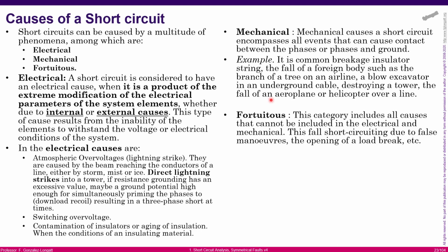For instance, at substation level, imagine that you have a circuit breaker and the dispatcher didn't realize that the circuit breaker was closed, and he tried to open the switch connected to that. Switches are not designed to interrupt currents, and as a consequence, you will create a problem with insulation, and then there is a single line connected to ground by a big arc, okay? Very dangerous situation, okay?